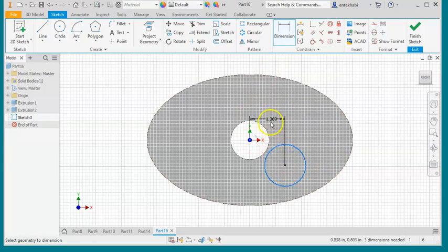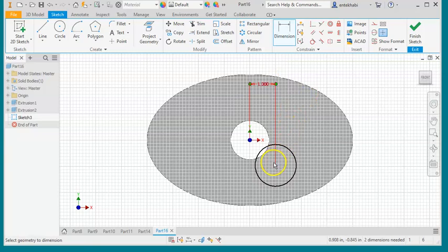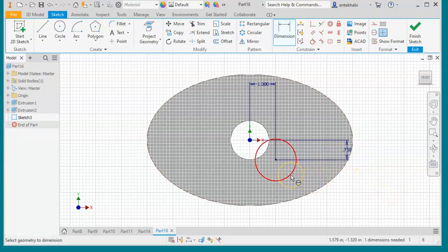the origin, given as 1 unit on the horizontal distance, and the vertical distance between the same point with respect to the y-axis would be 0.75. The circle should be a construction circle, which later defines the center of that adjustable hole. Select the circle and make it construction.